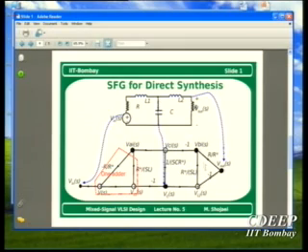And now we want to convert it, and here if you notice we have two adders. We can combine them into one adder, which is simpler, but then the adder that we implement using op-amps will have more inputs, meaning Vai, Vin and Vcs. These three will be inputs. So what is the component we use? Two things you can do.